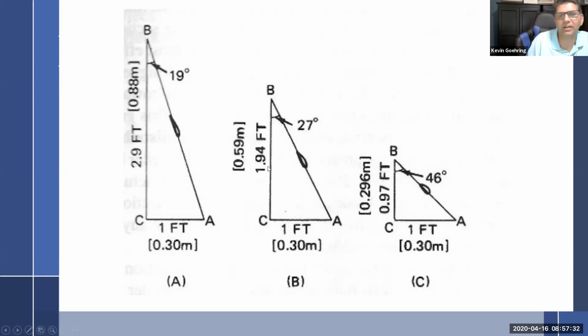Same thing over here. It rotated this, that 27. So that should be at 30 degrees to give us 3-degree angle of attack. And then 46 is where the angle of attack is. So the blade should be twisted to 49, right? 49 degrees about. So that works.